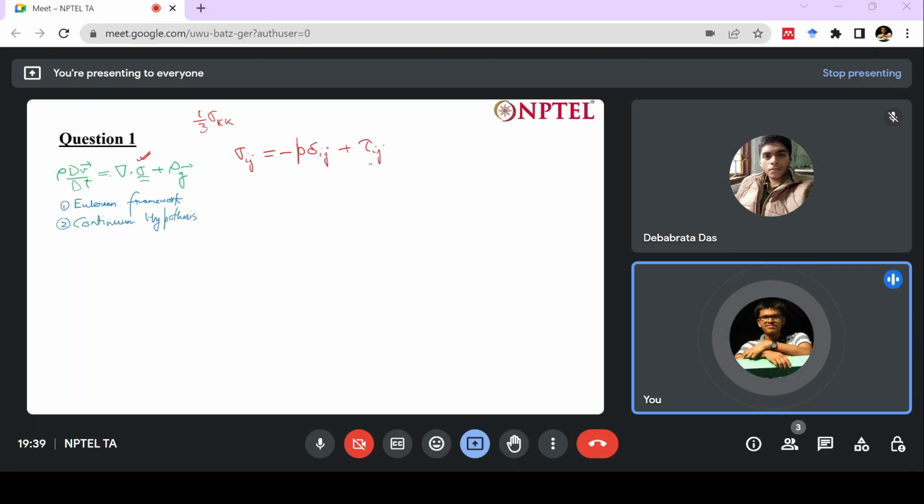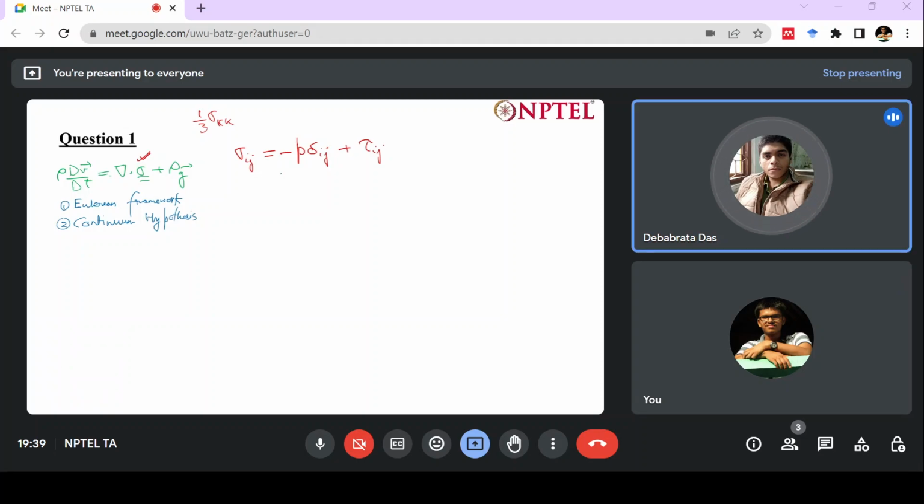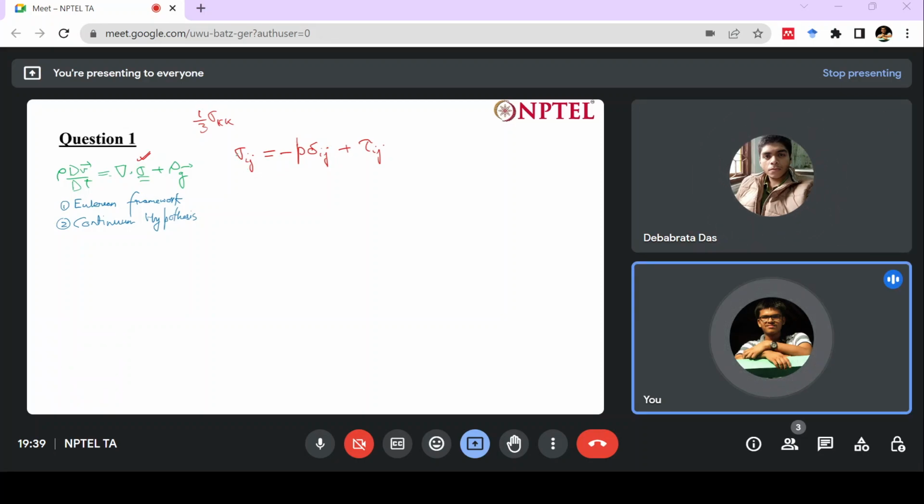Okay, what is tau ij? Stress. Then what is sigma ij? Sigma ij is stress, right? We are breaking stress down into two components. Tau ij is a special kind of stress, called the deviatoric stress tensor.